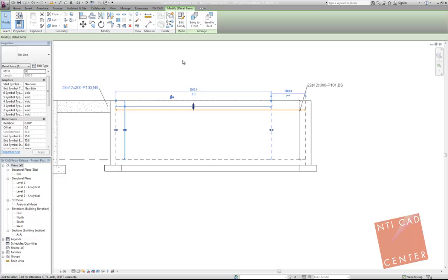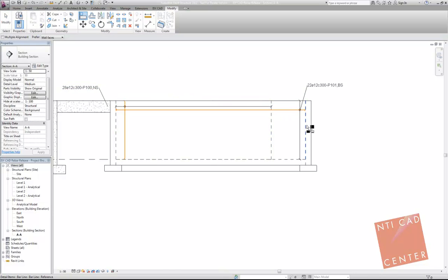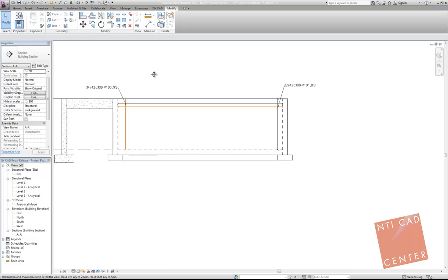I can lock these arrows using, for example, something which is called align, saying go here, shape handle, lock it, you see the number of elements changes, and when I do this, basically now my rebar will follow the external geometry, so for example the surface of the wall or something like this. So even though it's a 2D symbol, you can make it a logical sort of living model. If you change your geometry, the rebar will follow, the quantities will be updated.